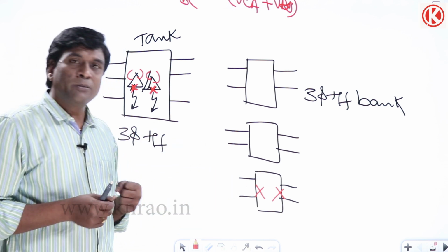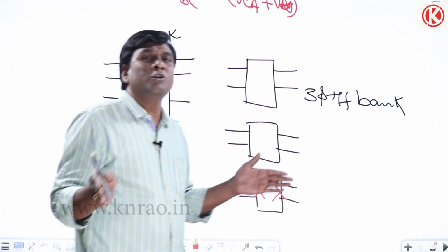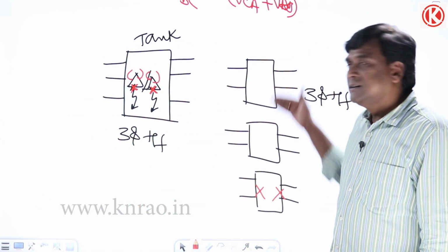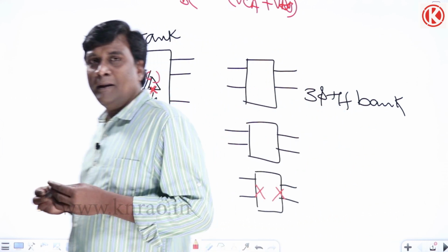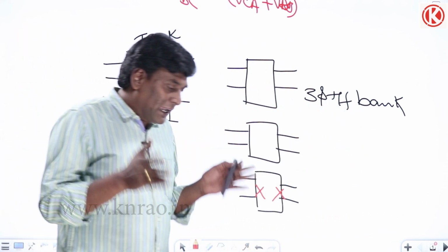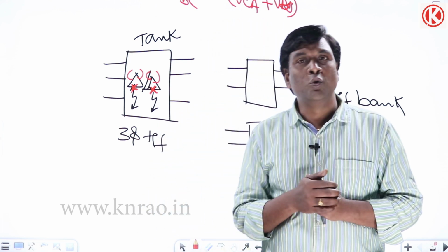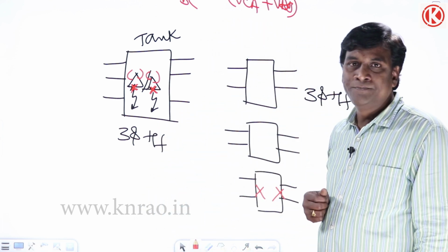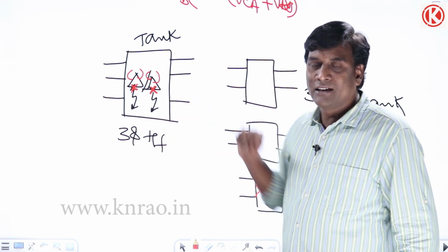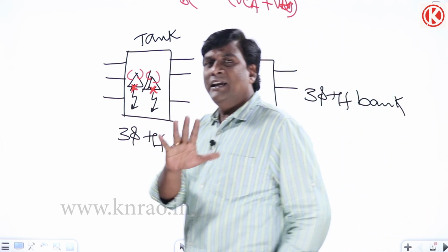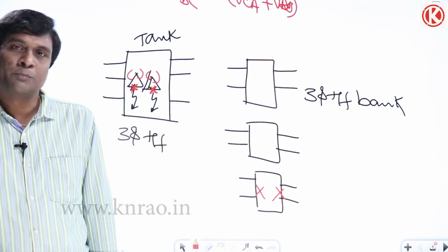Okay, now this transformer can go for repair work, and a bit longer duration you can maintain if it is a three-phase transformer bank. But where do we use a three-phase transformer bank? Okay, see here, if you have a huge capacity of load or huge capacity of demand, maybe in a single transformer tank I can design up to 3 MVA, for example, up to 3 MVA.